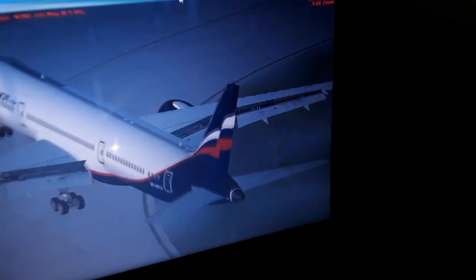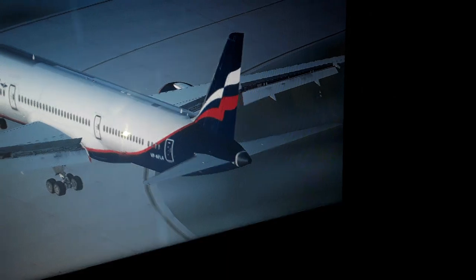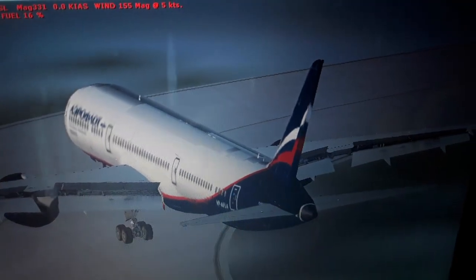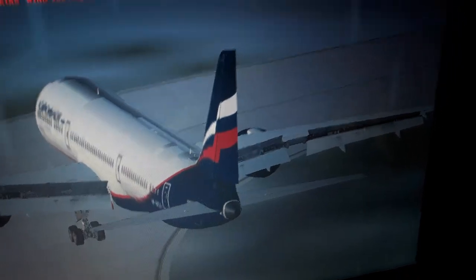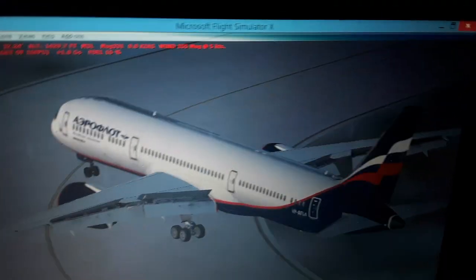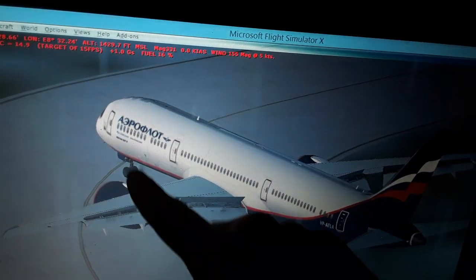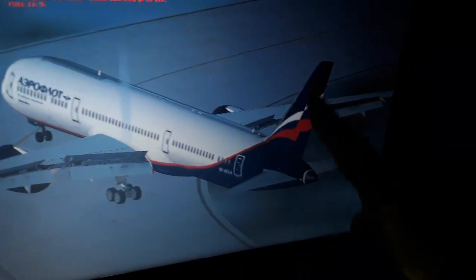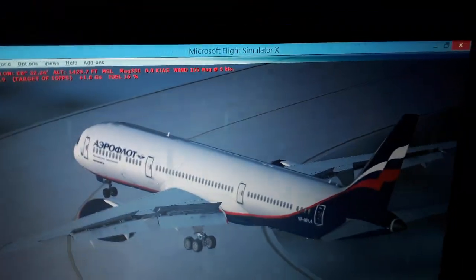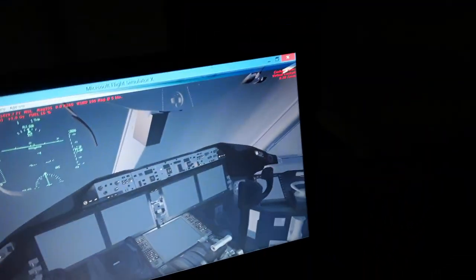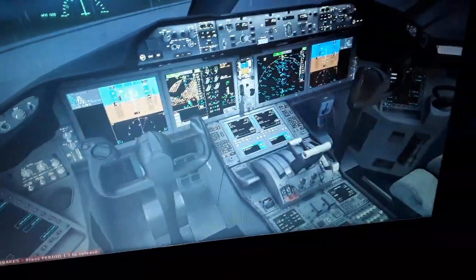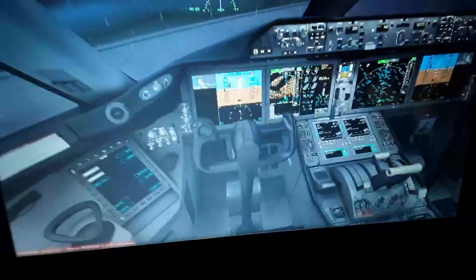We have the yawing axis. We can yaw the jetliner aircraft using the rudder pedals, as you can see. So we use left and right rudder like this input, and also on the ground only the nose wheel to make left and right turns together with the rudder. They're interconnected, so you can see here when moving the rudder pedals, either left and right turns like this, we also move the nose wheel, the tiller.